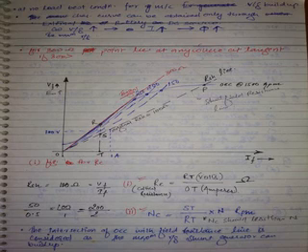Forget about all these critical resistances, all these things. This is over already. Now, just take again OCC and the original field resistance line. Only see these two. This is the original OCC at 1500. This is the original field resistance line. Both are meeting at a point known as P, that is the maximum capability of the machine to build up voltage, maximum level. Then, if you reduce the speed of the generator and plot OCC, then definitely this residual flux, this small value, will vary within a small voltage.